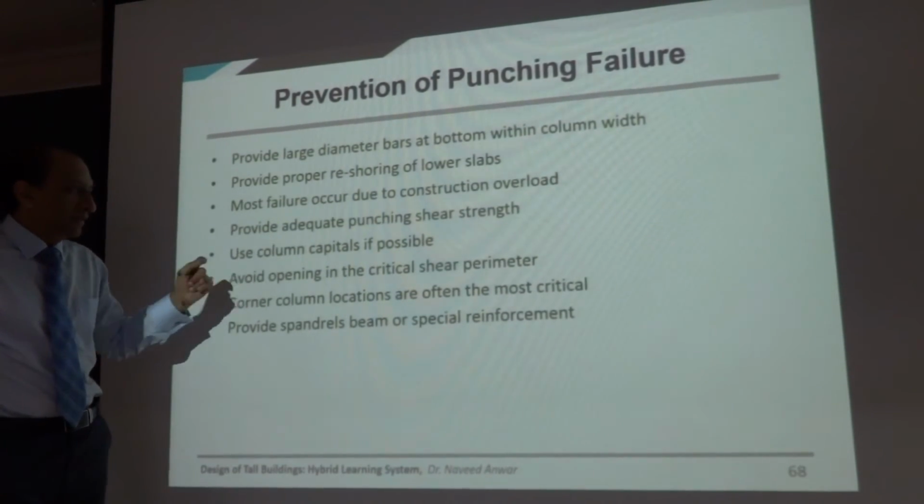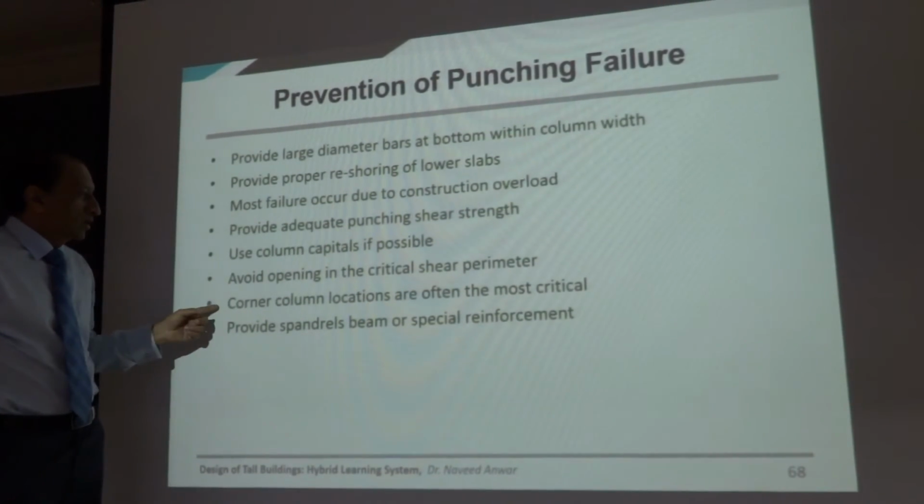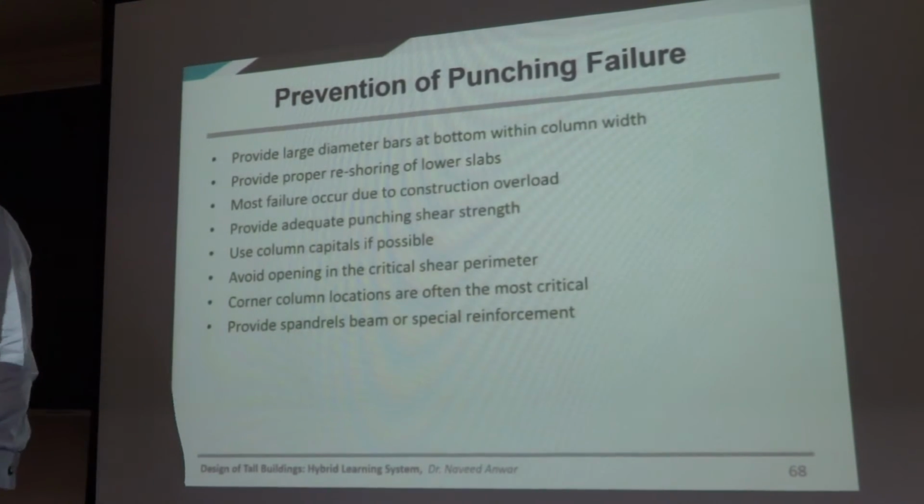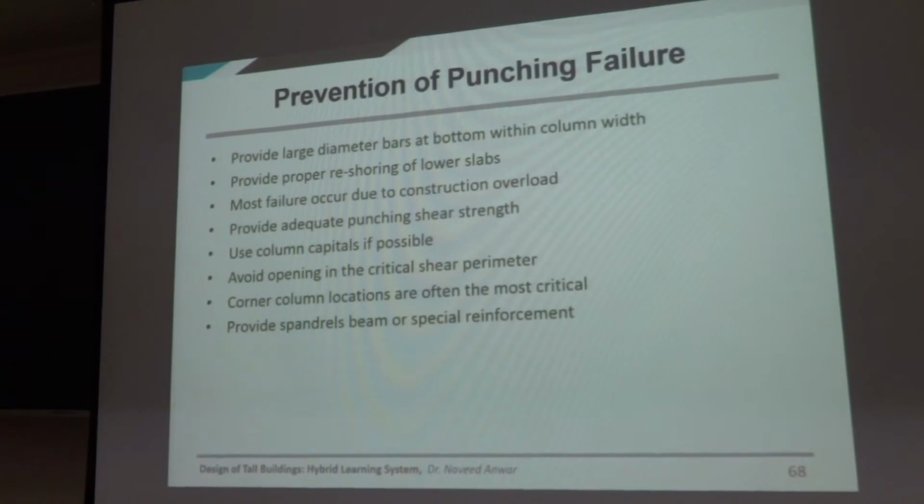Avoid opening in the critical zone. Do not put openings in that zone. Corner column locations are often the most critical because of the moment transfer. Double moment transfer there.